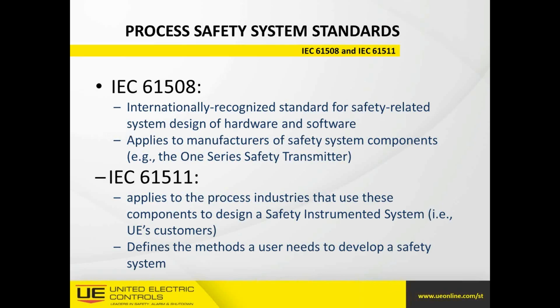Now that makes up the overall safety instrumented system. However, on the flip side, looking at the SIF, that is a safety instrumented function, and that is the method by which the risk of a specific hazard is reduced automatically using either a sensor, logic solver, or a final element. But a safety instrumented function will be one of those three items specifically. So there's the difference between an SIS and an SIF, both playing completely different roles in terminology, just as basic process control and SIS do.